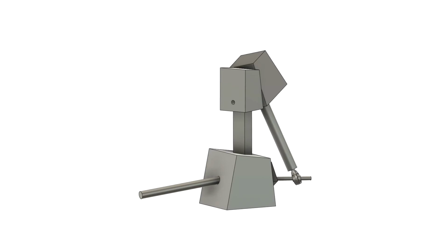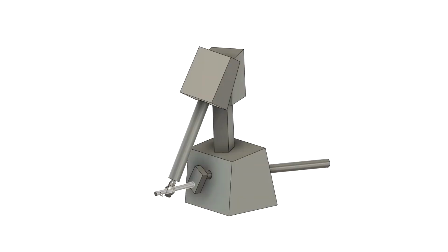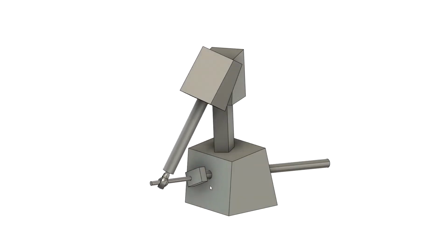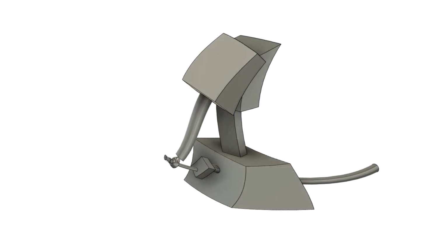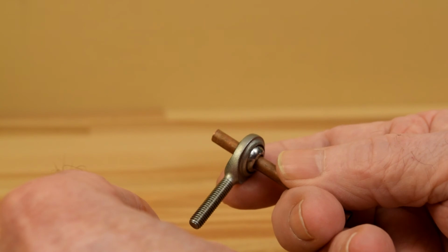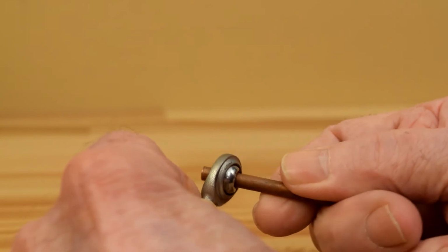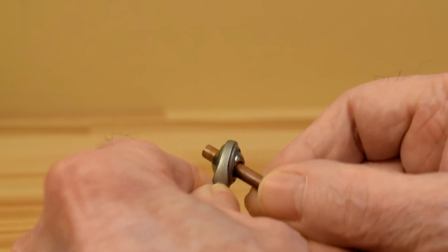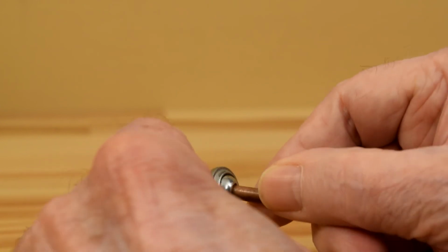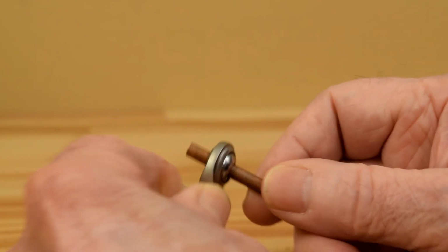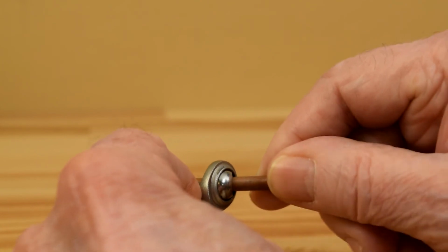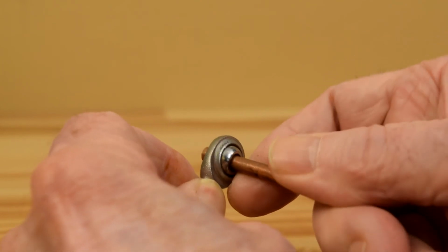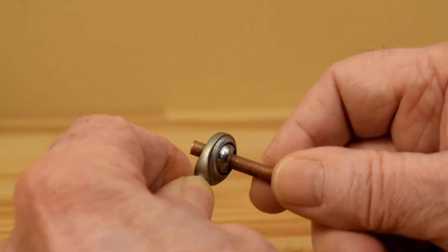I've toyed with the idea of making a small metal version of this engine. Just playing around, there are an endless number of shapes that might be employed, and the goal might be to create a bit of a Salvador Dali-like appearance and something intentionally providing a machining challenge. I purchased a small ball-joint rod end to see if it might work. This one uses a PTFE bearing liner, but is very stiff, and the friction losses aren't encouraging. A metal-to-metal joint, possibly freed a bit with Time-Saver lapping compound, might be more suitable.